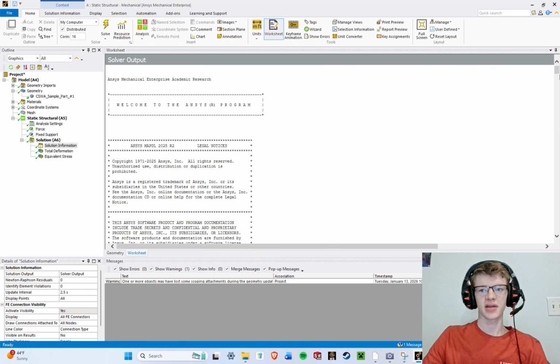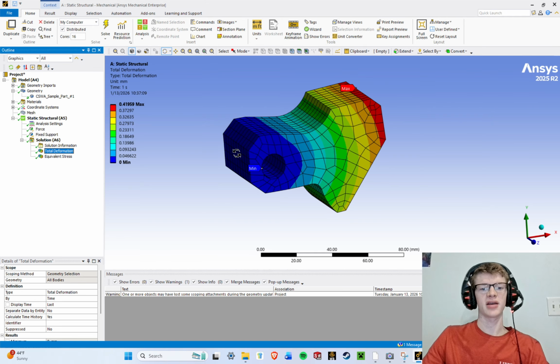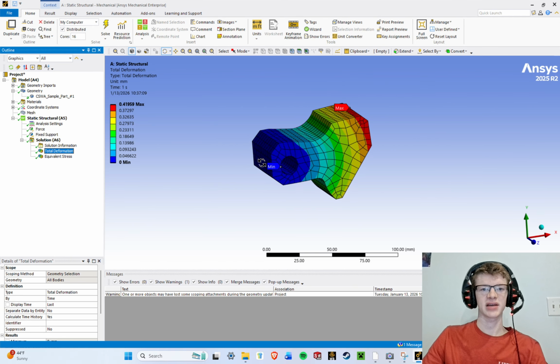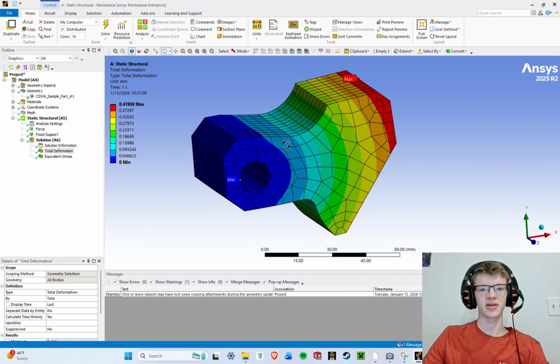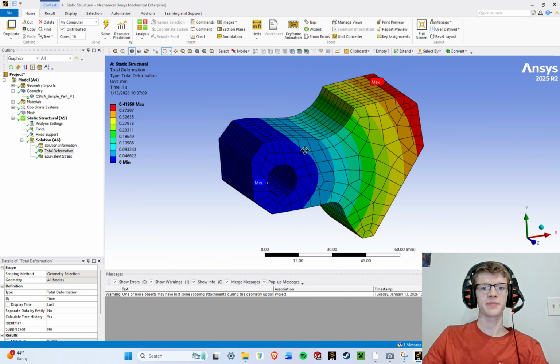So this is also a tip-off if you are doing this on a gaming laptop or something like that for college. Make sure GPU acceleration is off unless you have a GPU that Ansys accepts. This one took me a while to figure out, so I hope I'm saving you a little pain and grief by telling you ahead of time.